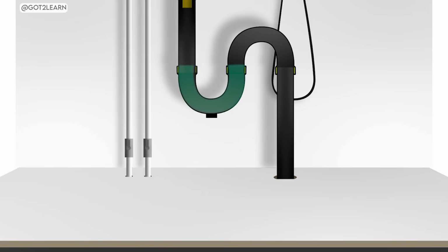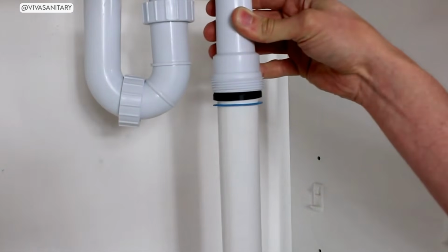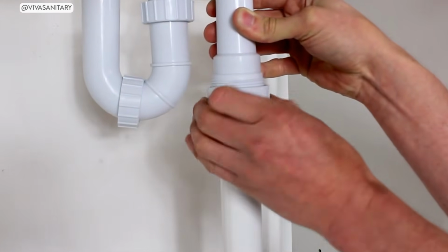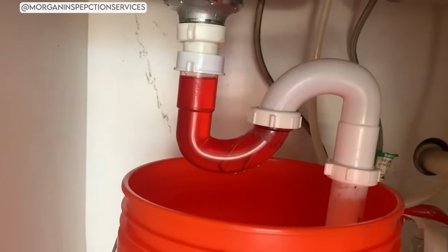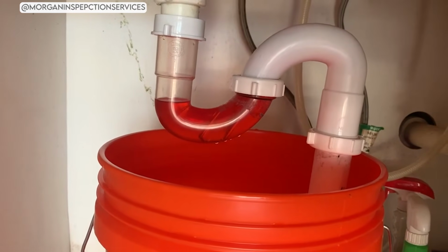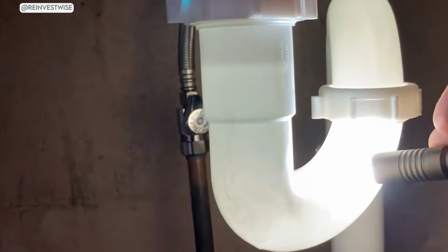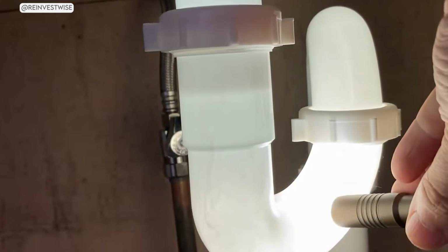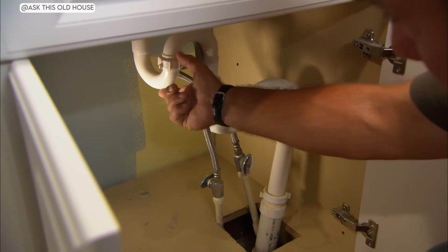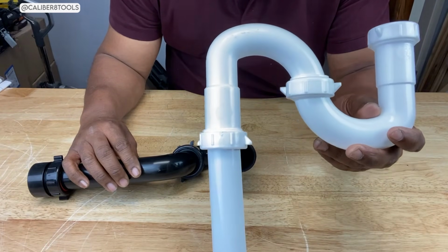The ninth thing I want to help you with is how to tell if you have an S-trap. This is the practical moment where you can actually check your own home. Go to any sink in your house and open the cabinet underneath. Look at the curved pipe coming down from the drain. Follow it with your eyes. If the pipe curves down, then back up, and then goes down again through the floor, you have an S-trap. The key indicator is that the pipe exits through the floor or goes downward after the trap bend.